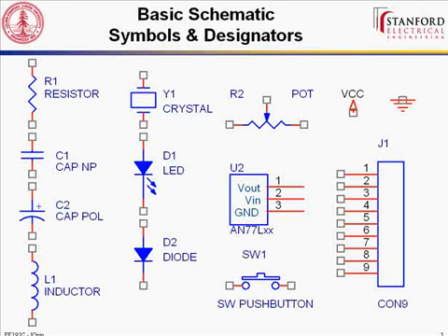So in the upper right there are 2 small symbols, and they're kind of obscured by the block indicating where the node is, but there's the VCC symbol, which is just a power symbol, and it doesn't have to be VCC. You can name it whatever you want and it will be a different rail. And then you have ground, and ground is ground, and you don't rename ground. All of your grounds are the same. But for example, you can have a 3-volt rail and a 5-volt rail that both use that VCC symbol, but they're still different.